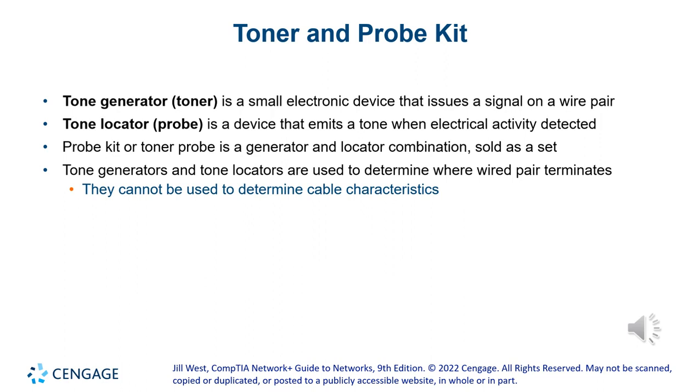That is very useful when you have a bundle of cables, say 50 cables in there, and you're trying to trace one cable that you don't know where it goes, or where the wire terminates, or when you want to identify those cables, number them, and document them. Then you can put a toner on one end, and go along the cables to see where the other end is, or which of the 50 cables spraying out is the one. So you use that to locate that cable.